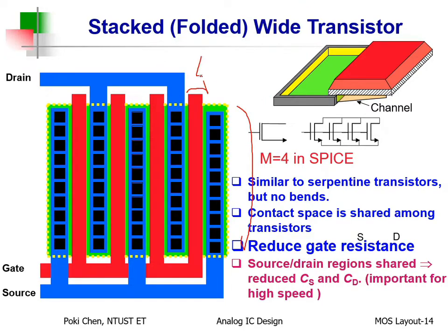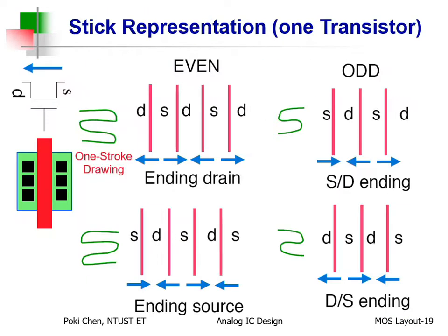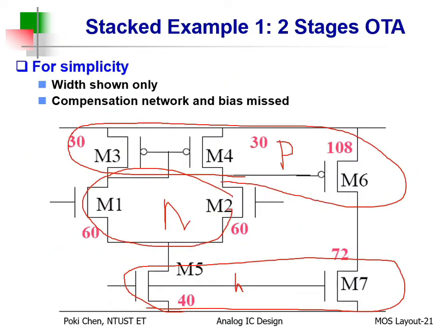Different length is okay, but different width is never okay. So we need to fine-tune as the IC designers. You have the right to fine-tune your aspect ratio, for example, here and there, to make the overall pattern easier to stack for layout.